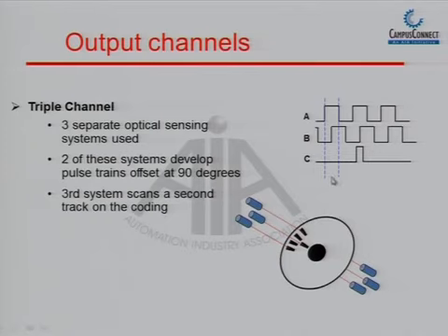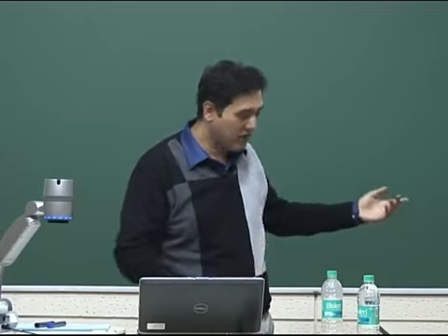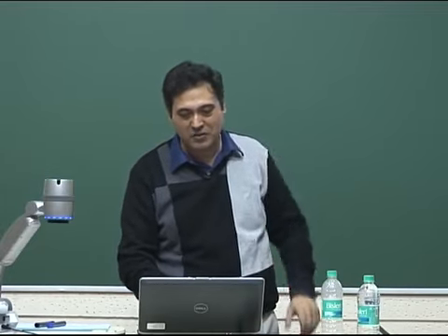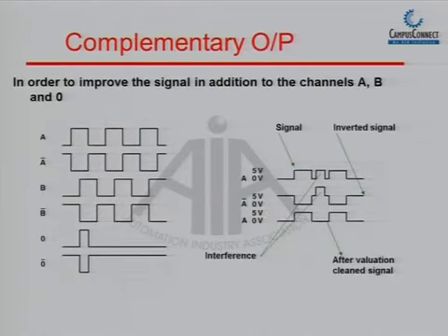So if you rotated an encoder and have moved a distance of 10 mm and there is a power failure, you have to move in an anti-clockwise direction so that you can reach the C channel, the zero channel pulse or marker pulse. This is not the case with absolute encoders. Again, since there is a possibility of noise interfering, each of these three channels has a complementary output, that means all three with opposite outputs. This helps to reduce the noise.